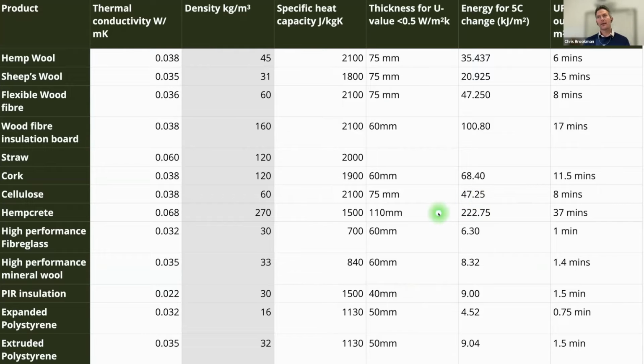Now, if you only live in a house intermittently, you're only going to be turning on the heating for short periods of time when you come back. So you don't necessarily want a building that is going to take ages and ages to heat up. So if you come back, say, it's relatively cold, certainly in the cooler months of the year, it might only be 15, 16 degrees inside. You want to warm it up. You want to get it up to 21, 22 degrees.